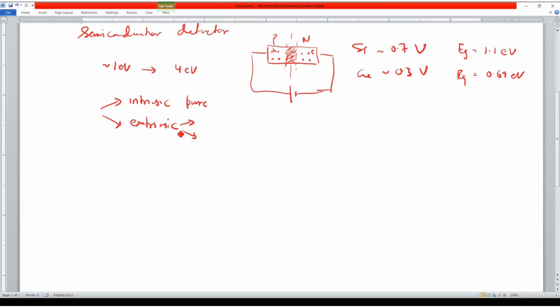When you add certain impurity intentionally, तो intentionally आप उसके site को disturb कर रहे हो. यानी silicon का आपके पास crystal है, so you want to remove a certain number of silicon atoms and put certain other things. So normally what we do, silicon is a tetravalent system, so we put either a trivalent or a pentavalent system. तो हम एल्युमिनियम की डोपिंग कर सकते हैं, फास्फोरस की डोपिंग कर सकते हैं, कोई और भी जिसमें हमारे पास पेंटावेलेंट या ट्राइवेलेंट का कैरेक्टरिस्टिक हो. So we get two different kinds of things, n type and p type.